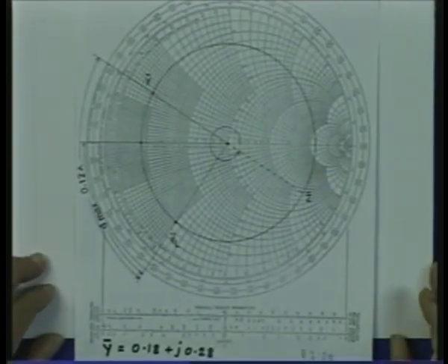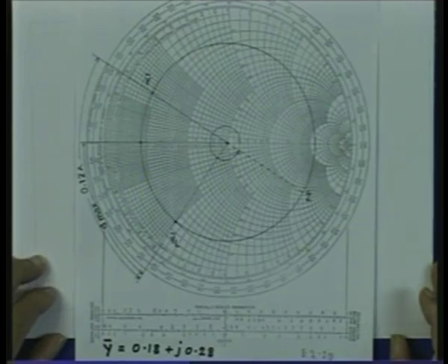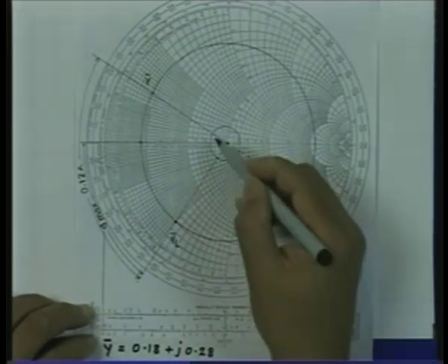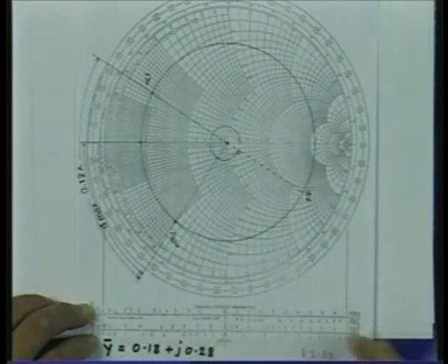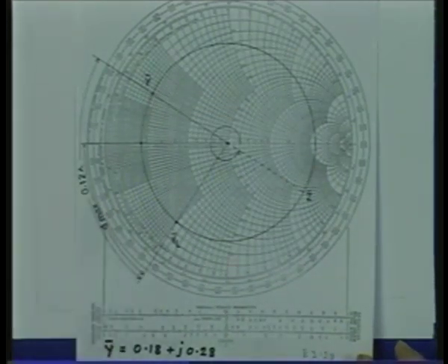To get the reflection coefficient, either I can calculate from the admittance itself, but we also have to find the normalized impedance at this distance. We know from the transmission line property that the normalized impedance inverts itself at a distance of lambda by 4. If it inverts the normalized impedance, that will become normalized admittance and vice versa.